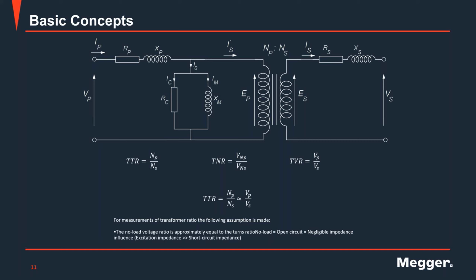That is not something that I will find on the nameplate or on the maintenance manual of the unit. Typically, as end users or the individual running the test, I don't know that number of any transformer. So what we are actually measuring in the field is the transformer voltage ratio, right? The TTR indicated on that last equation on the right.